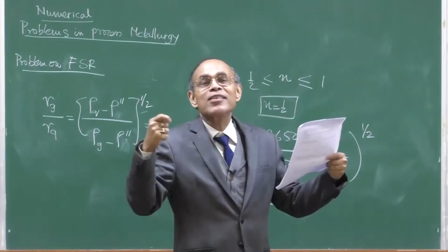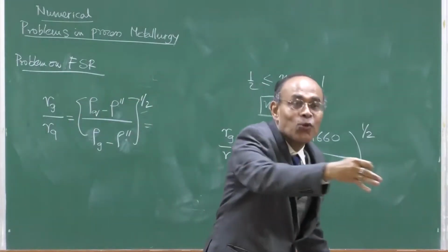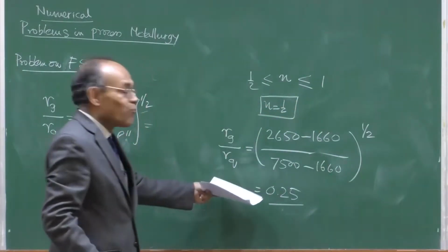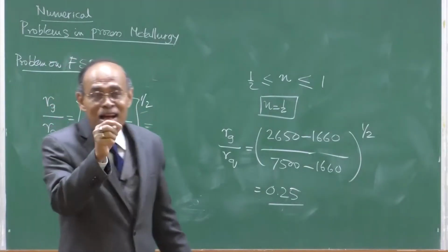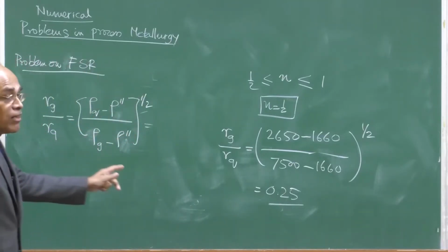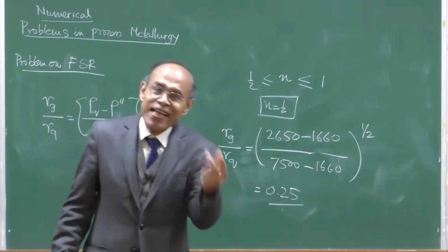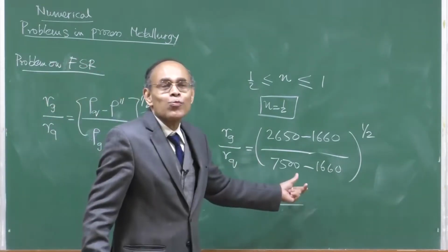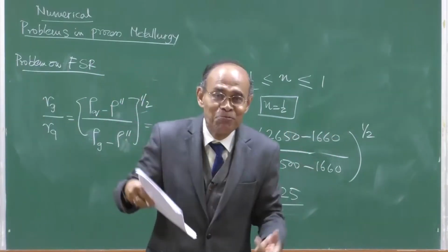Lead galena particles are mightier, the density is there, mass is there, so it is forcing its way through the medium, and as a result, even in the case of hindered settling, much finer particles are going to be settling. So, the conclusion is that real phenomena correspond closer to hindered settling, because we have to use a large tonnage of material.